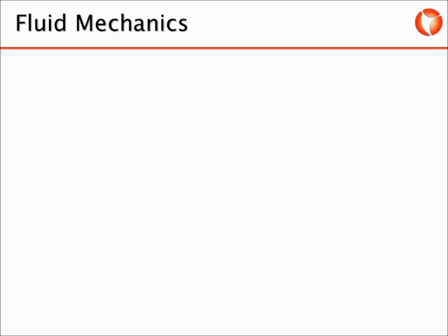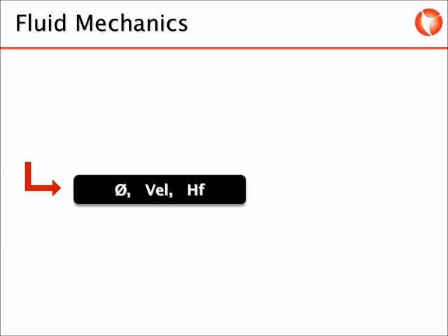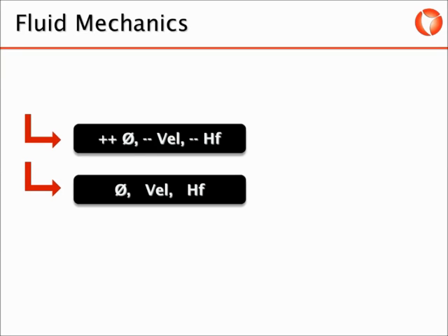There is not a unique solution when it comes to piping sizing. There are different solutions that bring different implications. Let's analyze the following. For a given diameter, a fixed velocity and pressure loss can be found. If the pressure loss of the system needs to be minimized, the velocity has to decrease, and therefore the diameter of the pipes will increase.